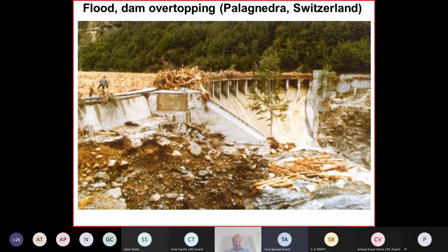because usually with a free flow spillway, you assume they are absolutely safe if the water would be clean. But here, I would say the deficiency is that the spacing of these spillway piers, there is a bridge across this spillway, is too narrow. So this floating debris blocked the spillway and it overtopped the dam, and you can see the abutment. There are some parts with loose material here. It's washed away here on the right, and also on the left abutment we have some erosion taking place.